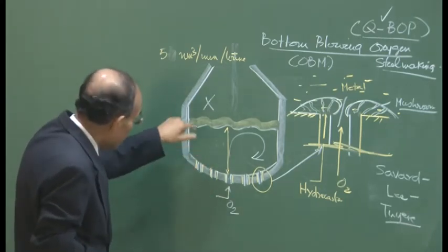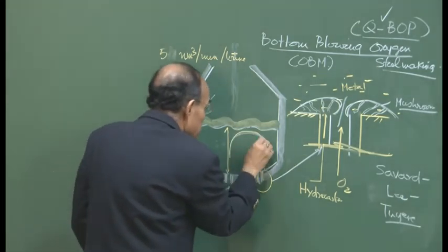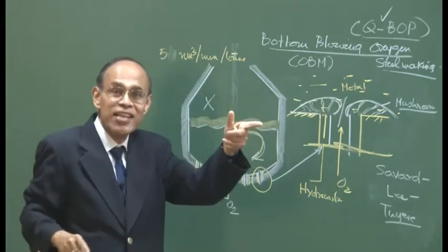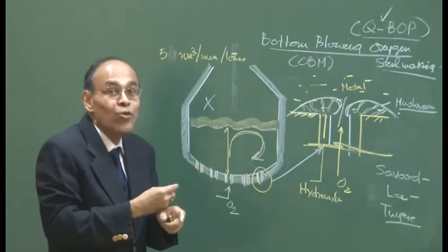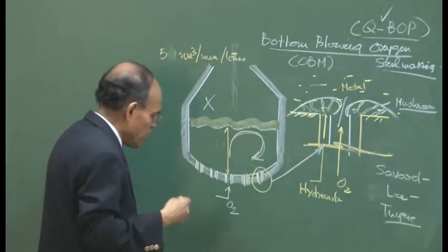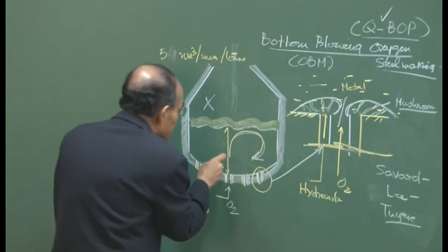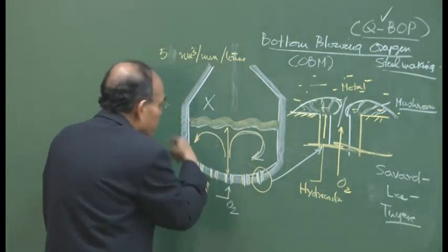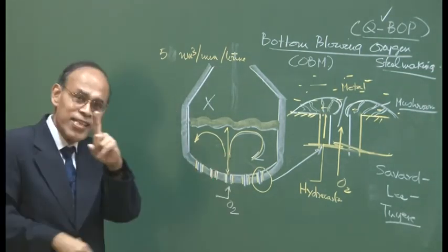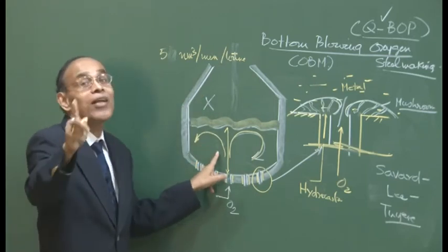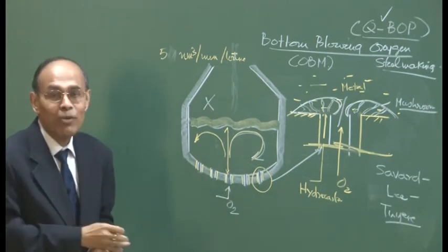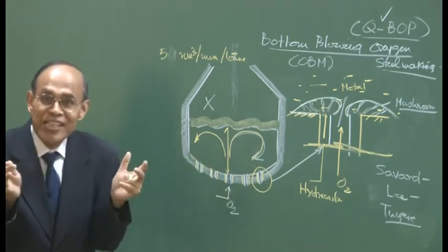So, a very intense amount of stirring and slag metal mixing, while the slag metal interfacial area is much larger in the LD steel making process. But the mixing will eventually determine how close to equilibrium the system is operating, and the agitation and slag metal mixing is far more efficient in the bulk of the liquid. So, you have only one single phase, no emulsion, but the bulk is very well stirred because of the correct design of the bottom tuyeres, and as a result the blowing time gets reduced here.